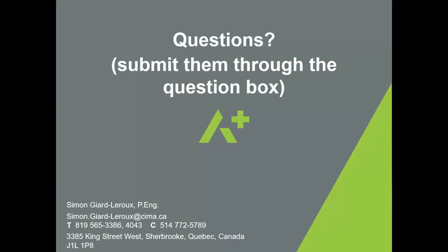And the second question is from Victor. He wants to know how the Z462 2021 compares to the NFPA 70E regarding the PPE categories. Well, for NFPA 70E, basically, there's no Category 5. That is the big change with regards to the US standard. So the lack of Category 5, and also the CSA Z462 does not talk about Category 0, which was a category that was present in the past.